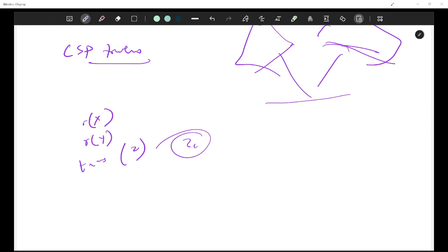If we are given the sun position and the receiver position, we compute the mirror normal using the reflection law and then the orientation matrix. Then we apply the constraint equations. We get 8 equations in 8 unknowns. We use Bezout's elimination theory, solve it numerically, and compute the leg lengths. So this is a classical inverse kinematics problem with constraints.